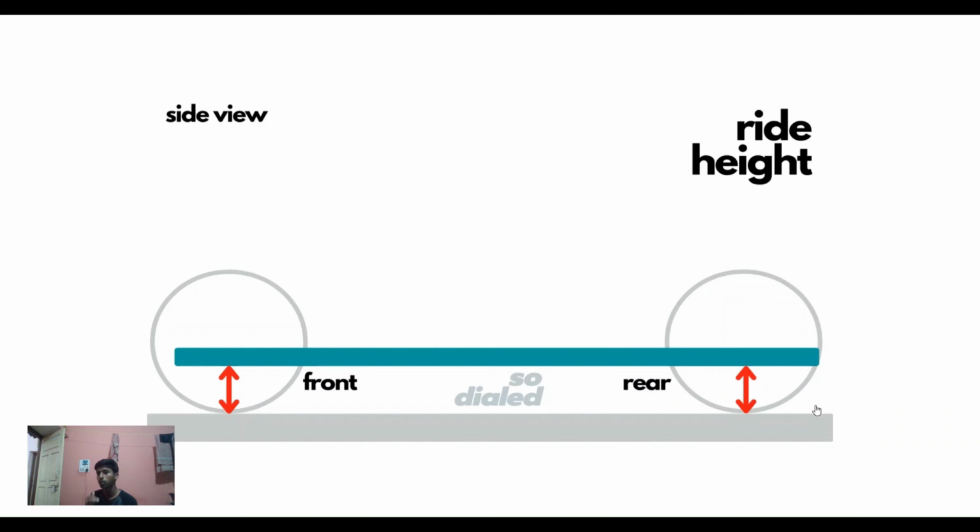And if you're talking about lower chassis heights and you want to make it more effective at that particular height, then make sure that you have a flat underbody. When you have a flat underbody, the amount of downward force acting on the car is even on all the sides. So that way, distribution of force is equal rather than one side experiencing more force than the other.